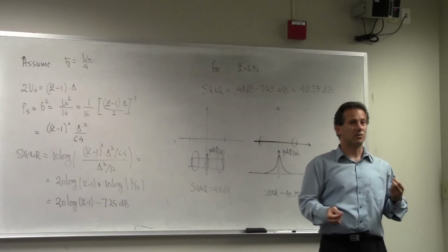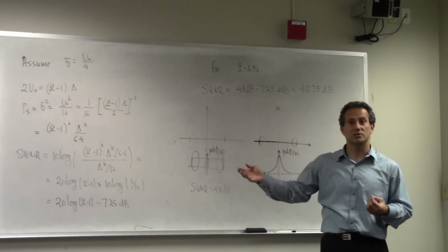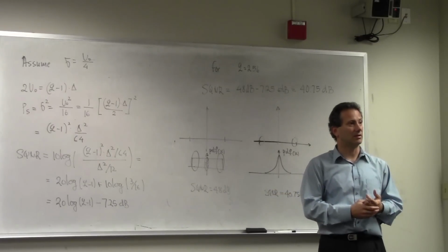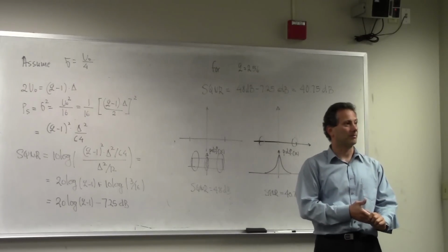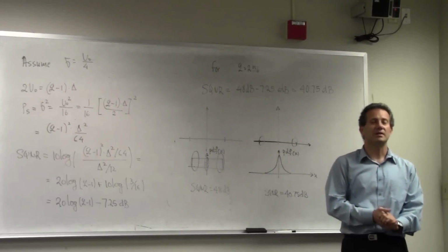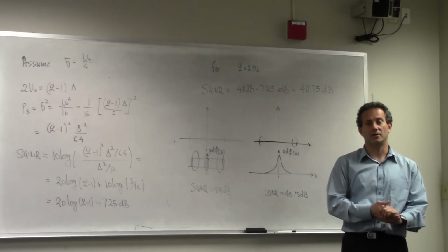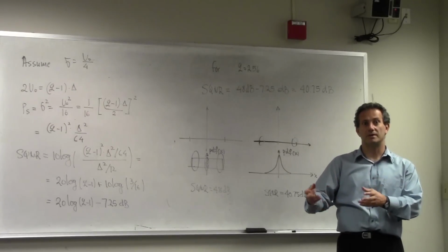You're building the case for non-uniform quantization, right? Why am I keeping this delta constant across the board? It seems that I have benefits that I can derive from keeping delta non-uniform. But what is the fundamental problem with it? You gotta know your input signal distribution. You gotta actually make a quantizer for every type of signal.